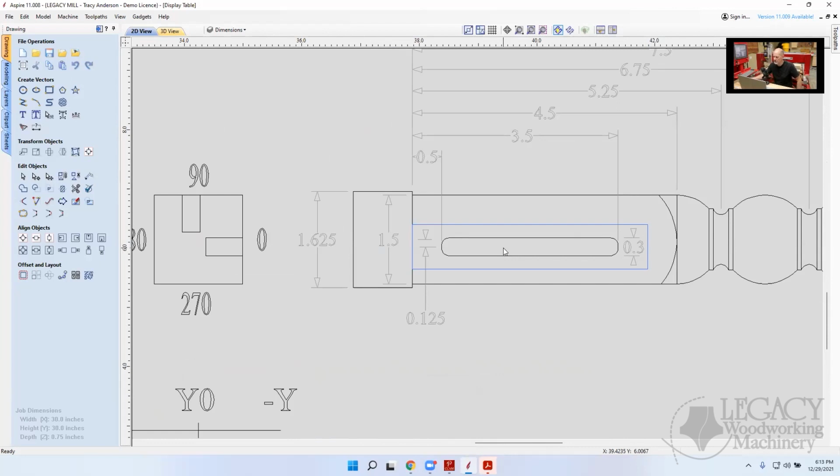And you can get that at different sizes. But what's nice is that now you can combine and use that tenon. So if, for example, you wanted a mortise on a very long part, and you can't stand it up vertically in the table, then you could use that Domino system to machine that. And then you can insert a floating tenon and join it up with something like this. So this makes a great combination between floating tenons and the Domino system, or you can do it all 100% in the system like we'll be doing here.